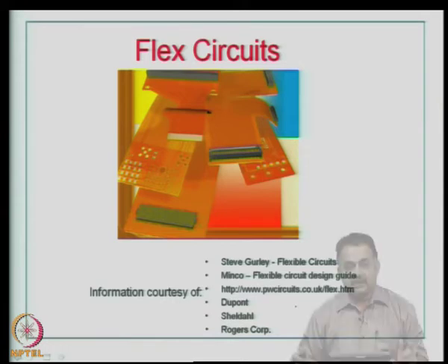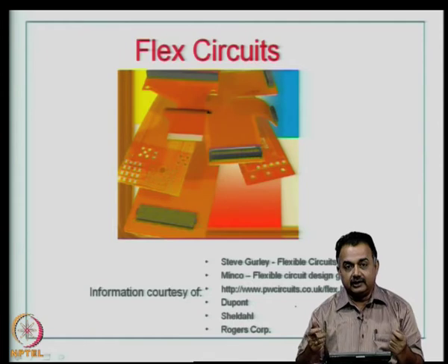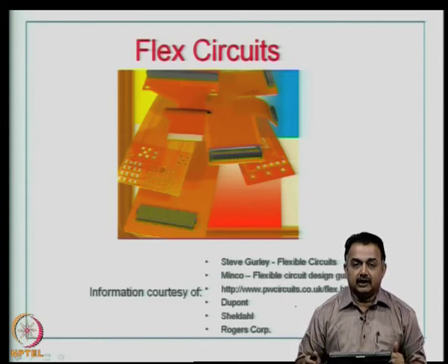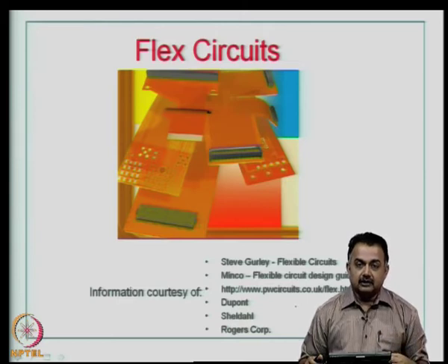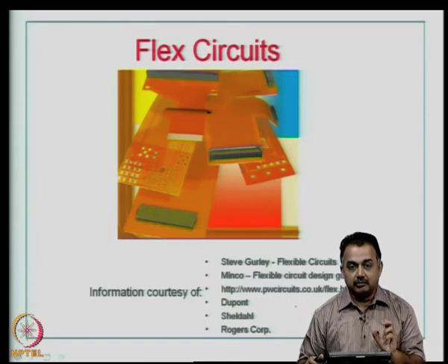So, basically as the term indicates, the substrate is flexible, you can bend it to a certain degree. Why should you have a board that is bendable? Because certain products have less space. The packaging requirement demands that the entire enclosure, mechanical enclosure requires a smaller space.